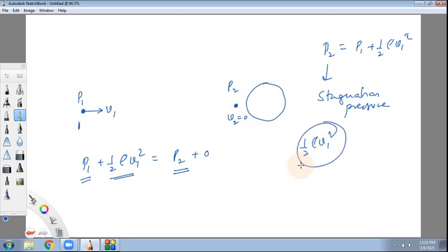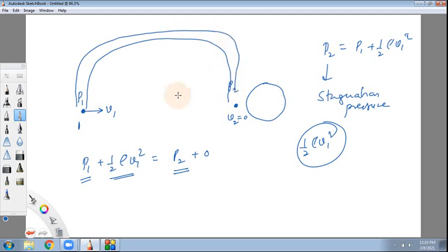Suppose I have a manometer which looks like this, a certain kind of U-tube, with a certain other liquid. My diagram is not very perfect. The differential pressure it is measuring shows up as the difference in heights of mercury.